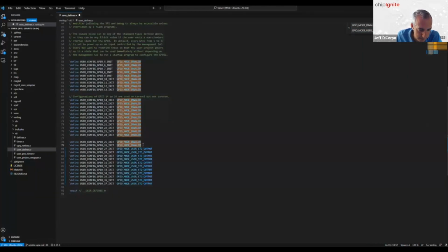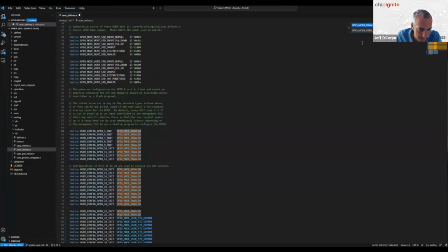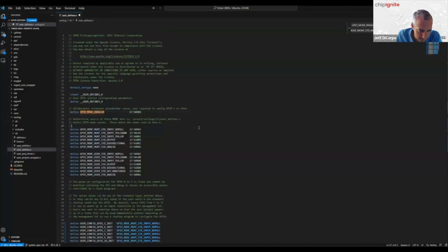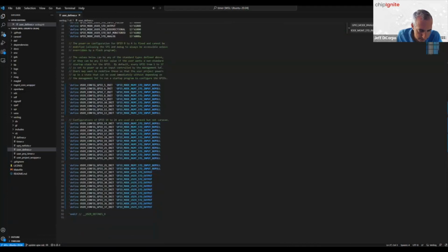GPIO_mode_user_standard_output. The other GPIOs are not utilized in our design, so we can just define the rest as GPIO_mode_management_standard_input_no-pull. Note that every GPIO configuration needs to replace the GPIO mode invalid setting with a valid configuration mode, even if the GPIO is not used.